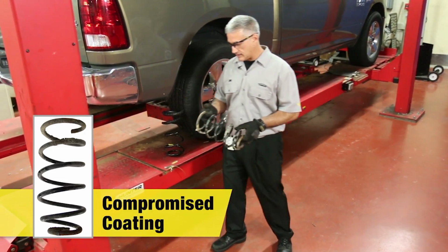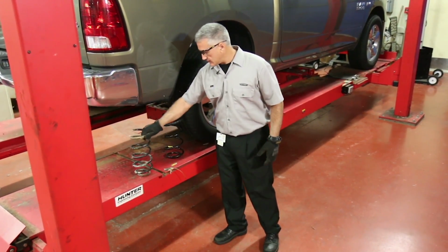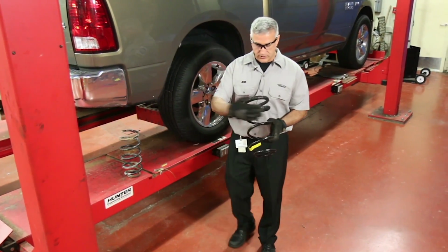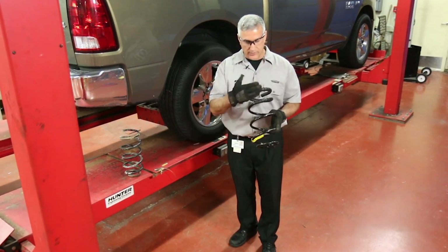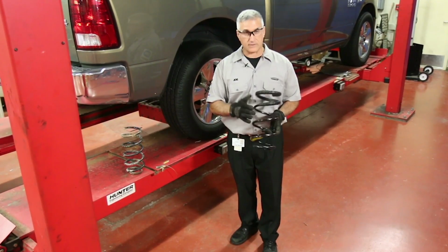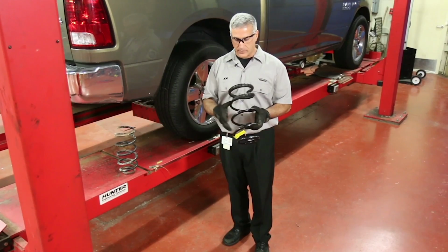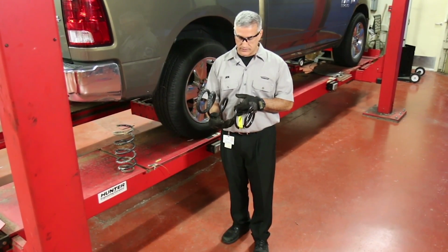Another thing that we're looking for is the ramp angle of the coil. It should be nice and even throughout all the different coils. If there's a kink in any one spot, that indicates that the spring has been damaged, either because of a missing jounce bumper or it could have been damaged during service.